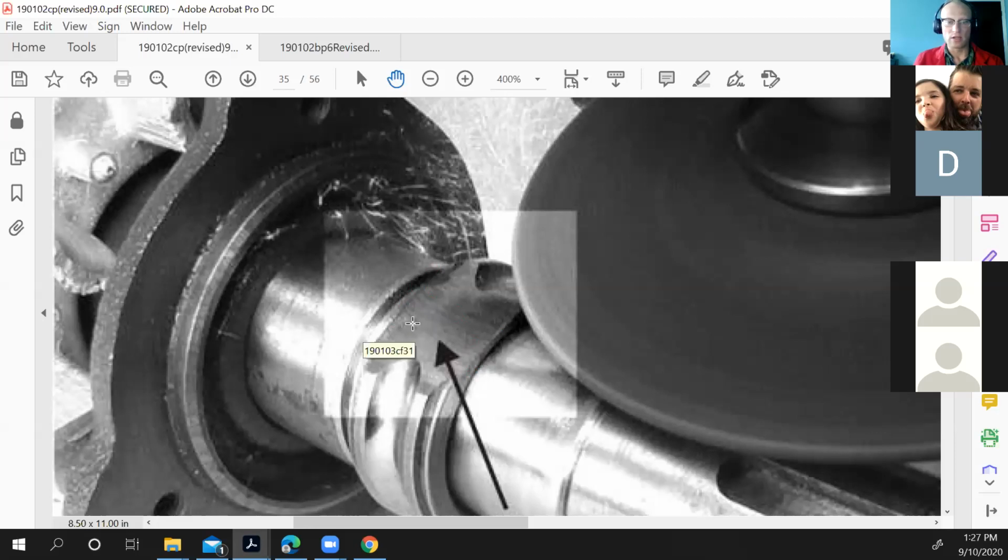Anyway. And if you did have to put heat on this, like if you tried to use heat to get this red hot to try and get it off and it wouldn't, don't try cutting it right away. The heat that you put into this race is transferring into this shaft. And if you put the torch to this, they're very close in temperature. And because they're touching, they will both burn away really, really quickly.